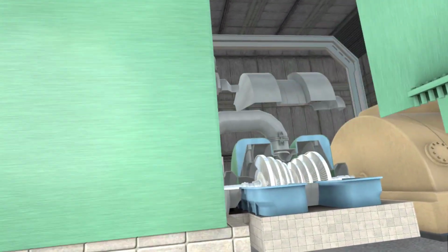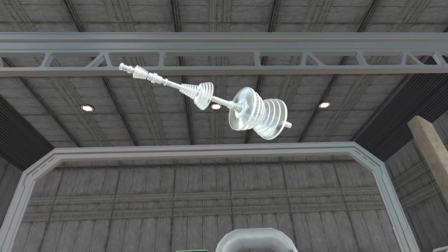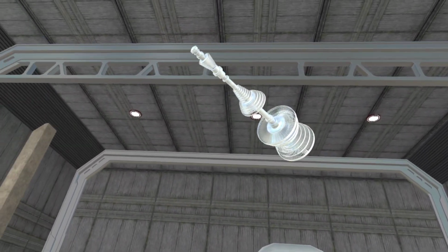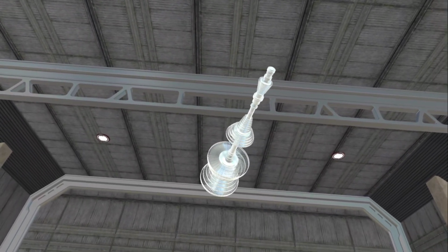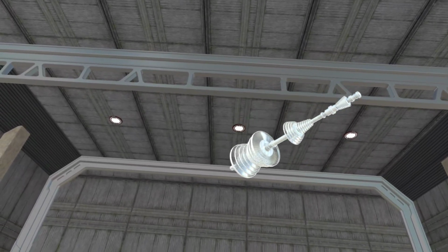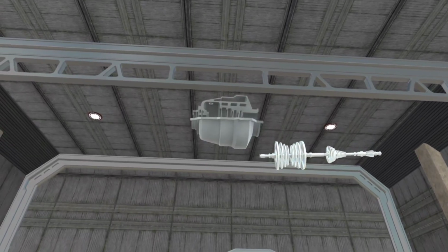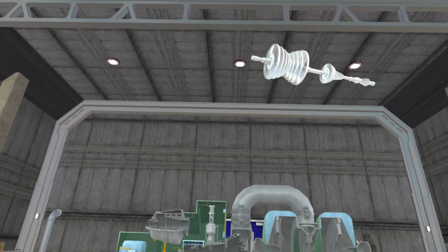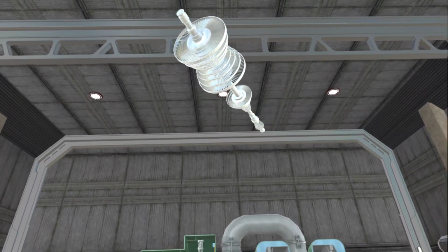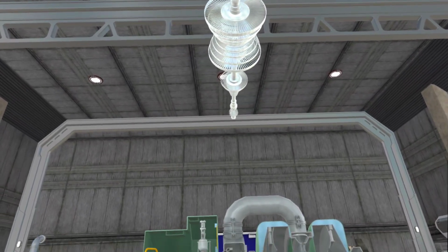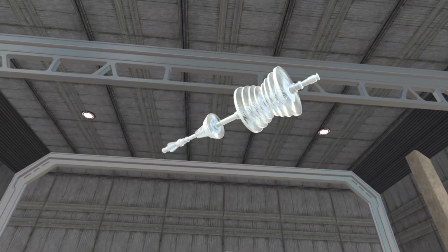A steam turbine lies at the heart of the power plant and is specially designed to extract thermal energy from pressurized steam, which is provided by a boiler. It uses the steam to perform mechanical work on a rotating shaft. The turbine has stationary blades on the casing and rotating blades on the shaft. The rotating blades rotate the shaft when steam blows past them. It further consists of a number of different sets of blades or stages, each helping to extract more energy from the steam before it gets exhausted.